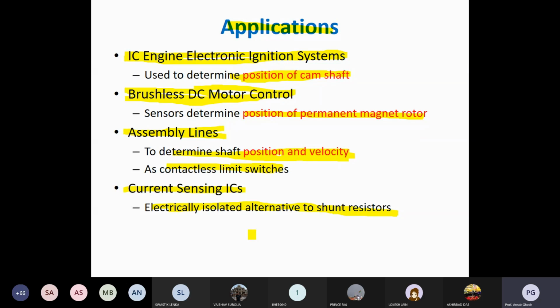Anytime, any faults may appear in your power circuit if there is no isolation between your control circuit and power circuit. Basically, the control circuit is designed based on analog electronics instruments. So if any problem occurs, a direct fault occurs, that fault comes directly from your power circuit to your control circuit.